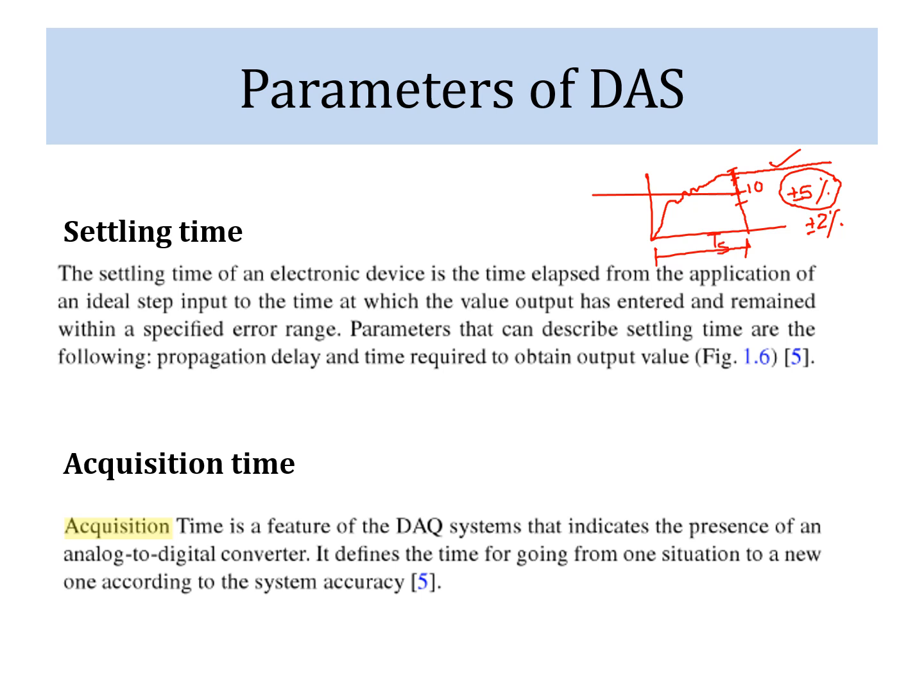Now comes one new term, that is acquisition time. We know that in most of the data acquisition systems, because they are built around digital systems, we have to have A to D, that is analog to digital converter. So, there is a time when analog signal is being sampled by the A to D. Once it is sampled to a particular level, let us say at this level the signal was sampled, it will be held for some time at this value only, and during that time this analog signal is converted into digital 1 0 0 0 1, something like this.